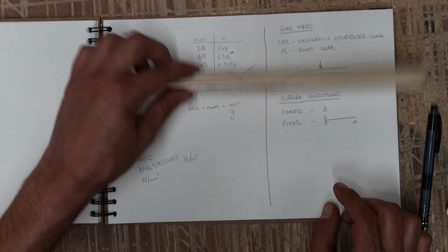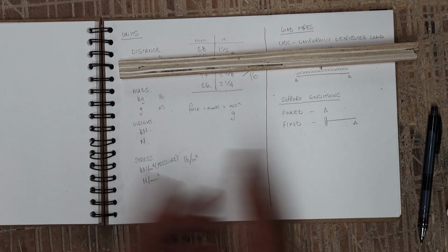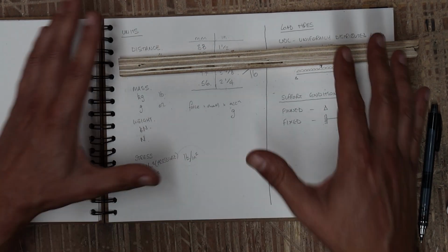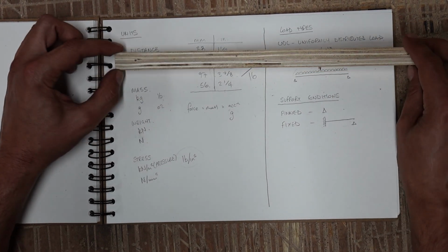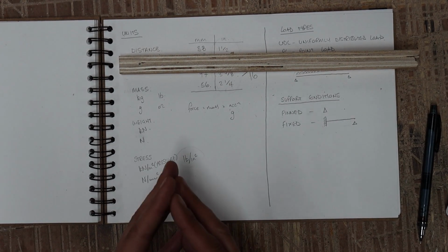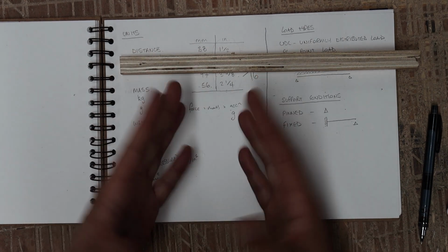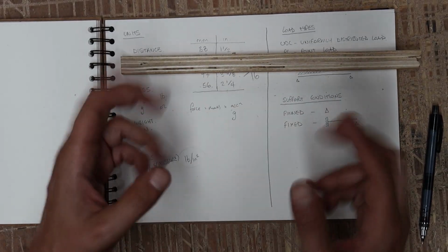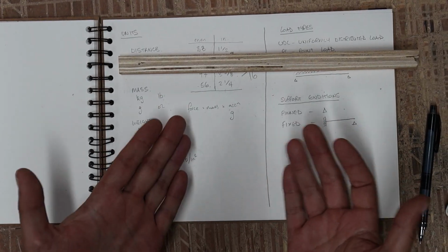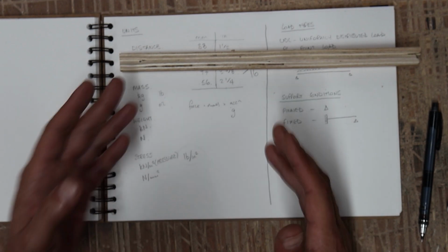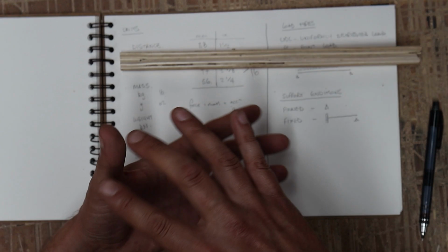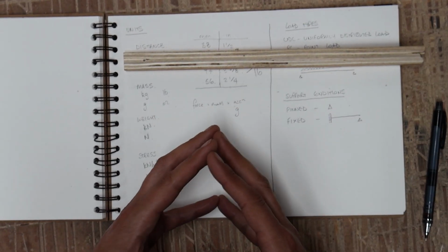That's all allowed for. Now, one thing to note is that we, as structural engineers specifically, are always trying to maintain an equilibrium of force. And the reason is that when something is out of equilibrium from a structural perspective, it becomes, technically speaking, a mechanism. Our first job when we're designing structures is to prevent the formation of mechanisms, or collapse mechanisms specifically.